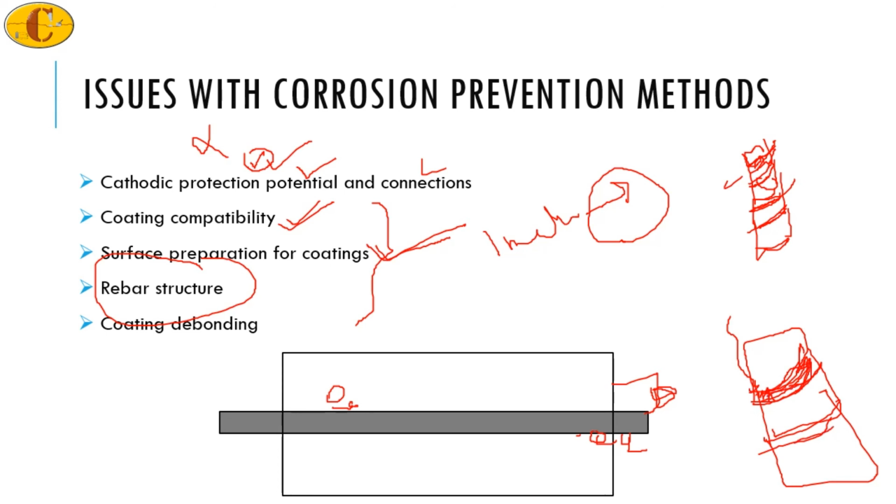Sometimes, if you use polymer coatings, these threads, which usually have a zigzag structure, will get blunted out because of the coating layer. Because they are blunted out, the adhesion between the upper concrete and the underlying thread is completely lost. So you will lose the mechanical locking that is expected between the concrete and the rebar structure.